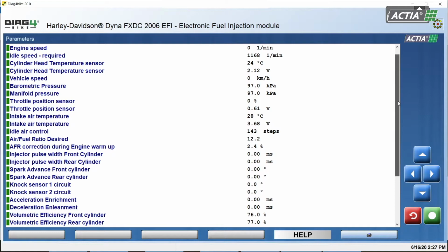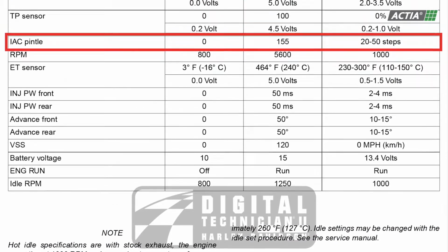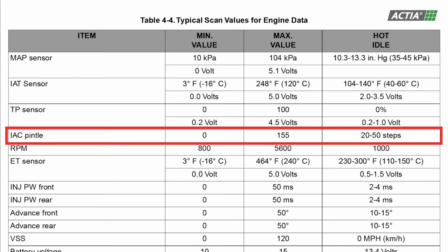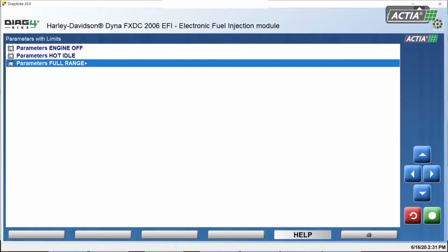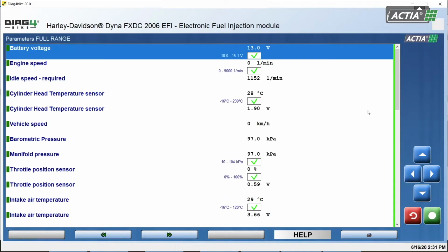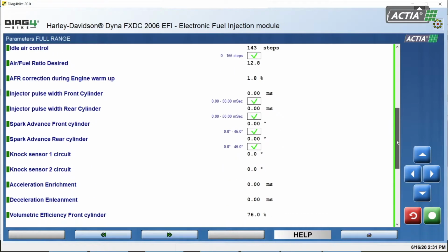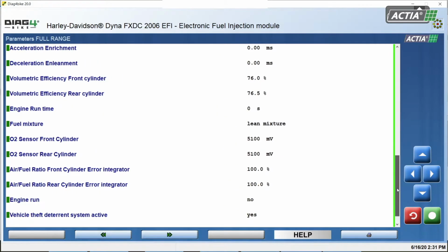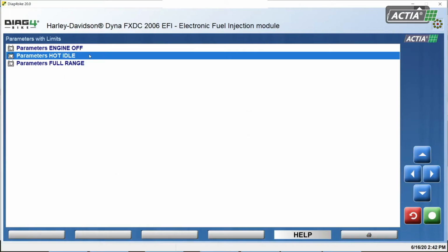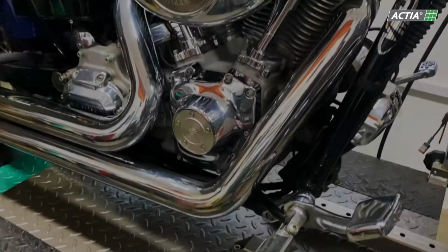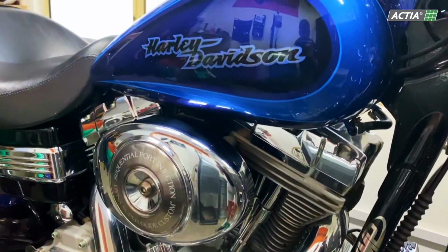In the event of a mechanical fault, stuttering, of the idle regulator, the read values will be higher than nominal. This is caused by the engine not being able to make use of all the impulses from the control unit, which causes the control unit to repeat these impulses more frequently. On the opposite end, leakage in the intake tract under the throttle valve will be indicated by a lower IAC step value than nominal.